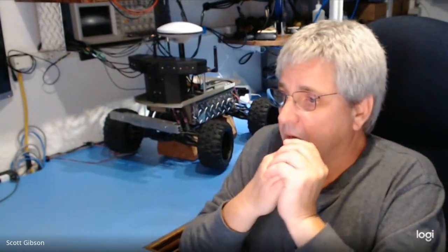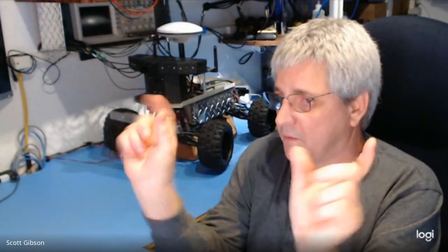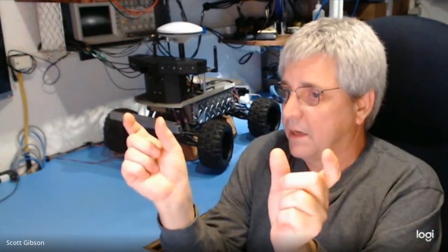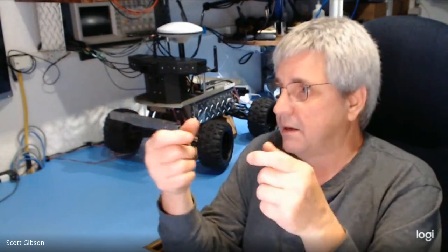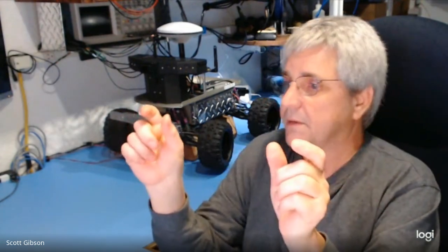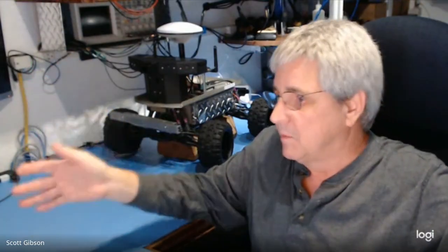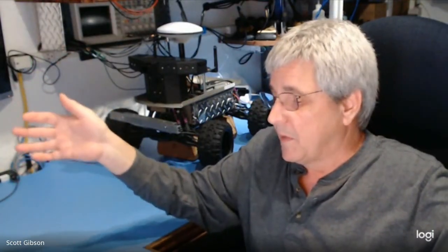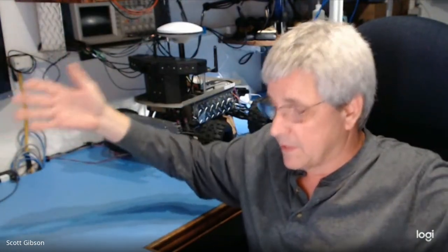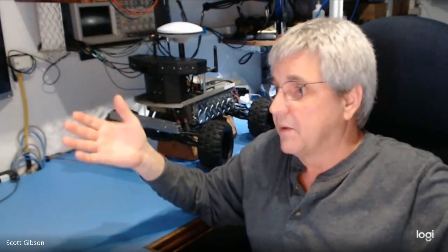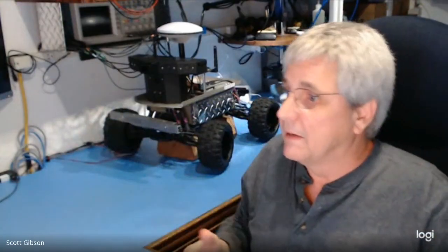So, what I'll do is once I get a hit on a cone, I rotate the sensors in a little bit. And then when I'm navigating and using them for obstacle avoidance, I'll rotate them out some so I have a wider field of view. But realistically, anything outside your wheel well or wheel distance, you don't care about anyway. I can drive right by something as long as I don't have to run over it, or hit it.